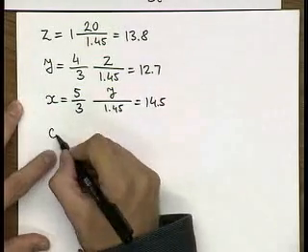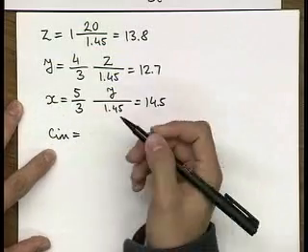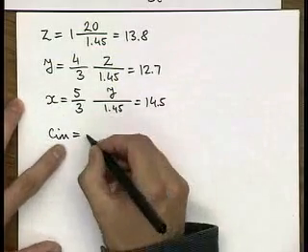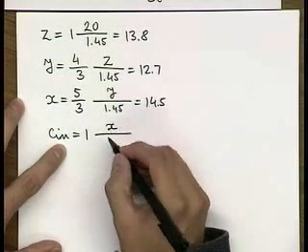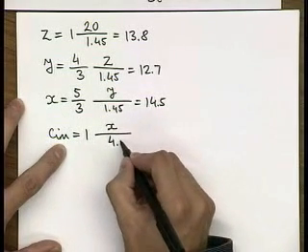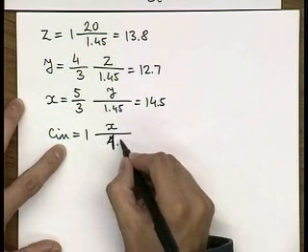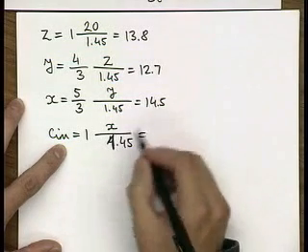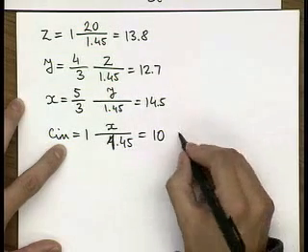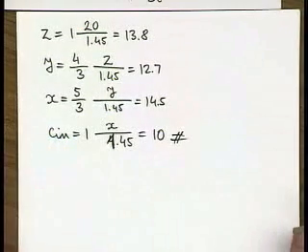And then we can finally verify the input capacitance of the first stage just to make sure everything is consistent. Logical effort of an inverter is 1, and the output capacitance is X divided by stage effort 1.45, and these give 10, so we are done. Everybody clear with this?